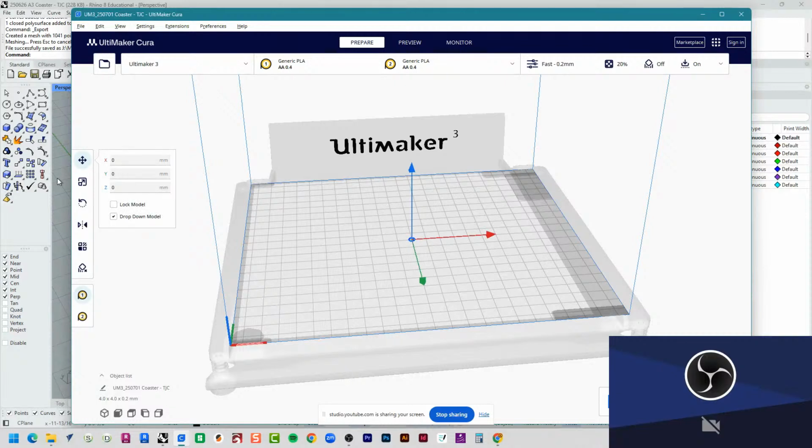If I click on it, on the left side, as you can see, everything's in millimeters, and it says 4 millimeters. X is the width in the X, Y is the width in the Y direction, Z is the thickness or the height in the Z direction. Right now it's giving me a 0.25 millimeter thickness, which is really, really small.